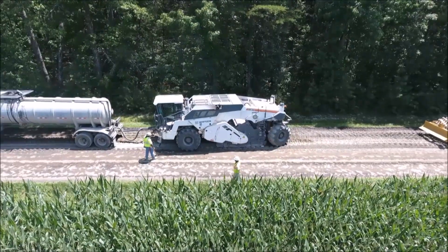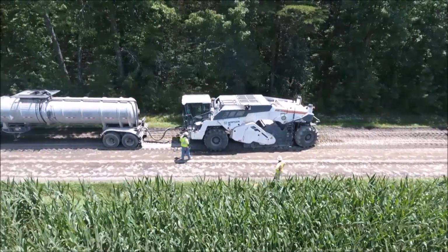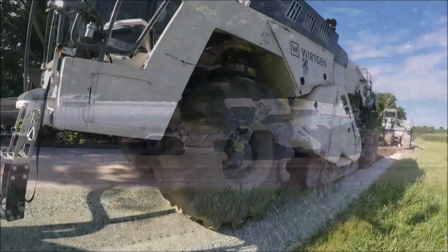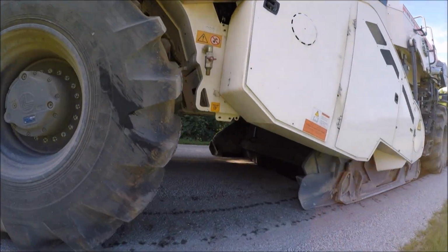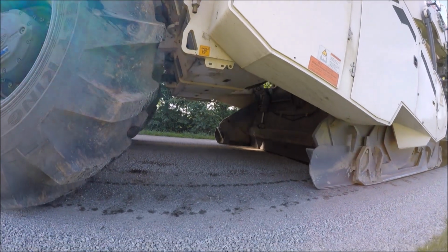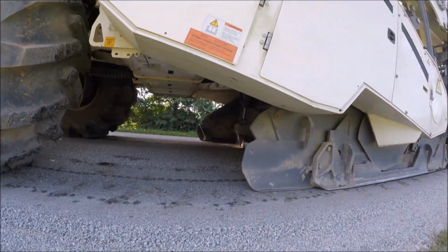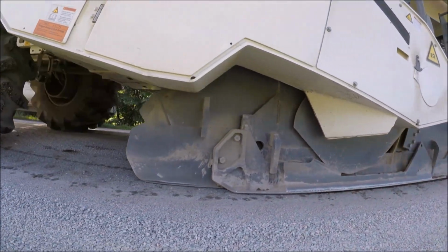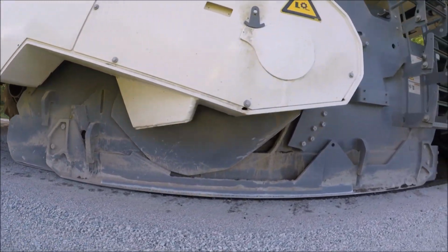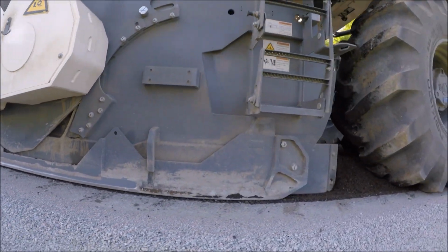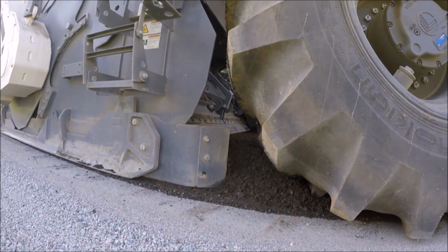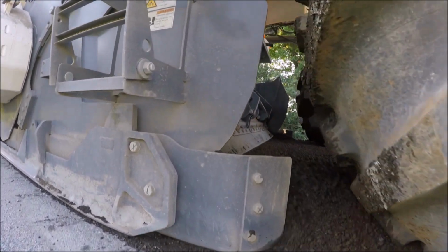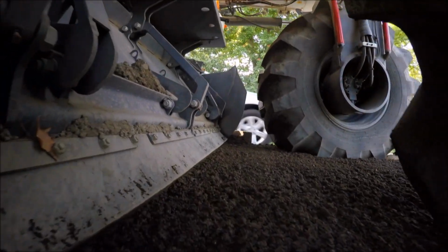You're taking all that material and pulverizing that road. Again, you're doing a full reclamation process where you're incorporating that subgrade soil, the stone, and the asphalt all in one pass. Here you make an initial pass, and we're going to break this down later on. We're going to segment some of this, but just to get an idea, a quick overview. What you're doing is pulverizing the existing roadway so you can make the grade corrections you'd like to do. You can see the gradation.